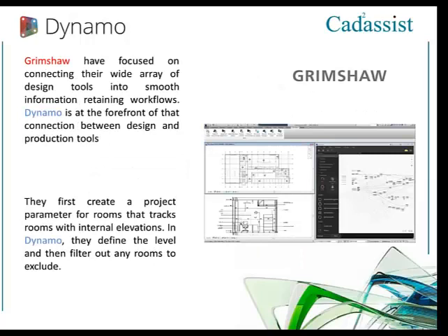Finally, Grimshaw Architects. Dynamo is also absolutely central to their strategy for using Revit, and they're integrating Dynamo into virtually everything that they do, and they're continually finding ways of using it to save time. One great example they wanted to share with us here is, well, I guess if you imagine for a second how long it takes for you as a Revit user to place interior elevation markers throughout a large project.